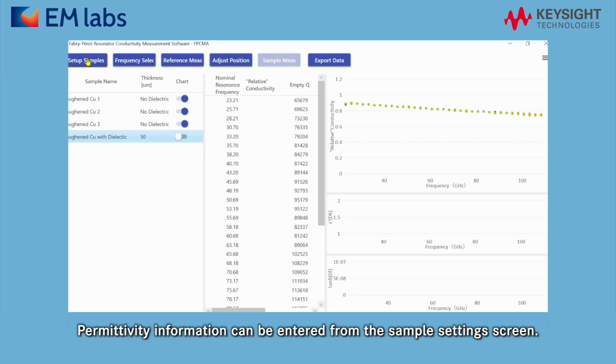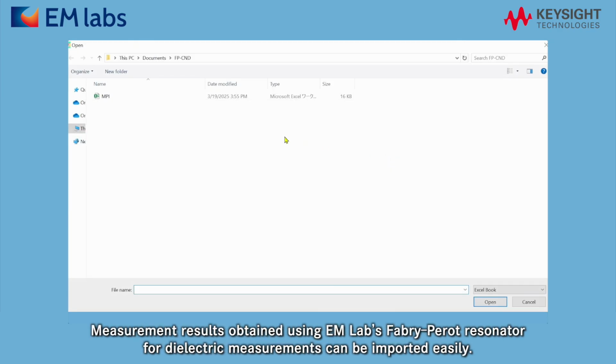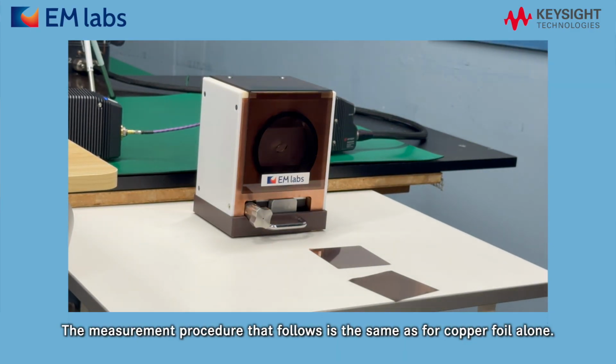Permittivity information can be entered from the sample settings screen. The polyimide used in this example has a thickness of 60 micrometers. Measurement results obtained using EMlabs Fabry-Perot Resonator for dielectric measurements can be imported easily. The measurement procedure that follows is the same as for copper foil alone.